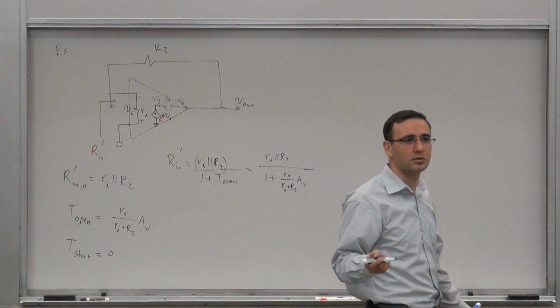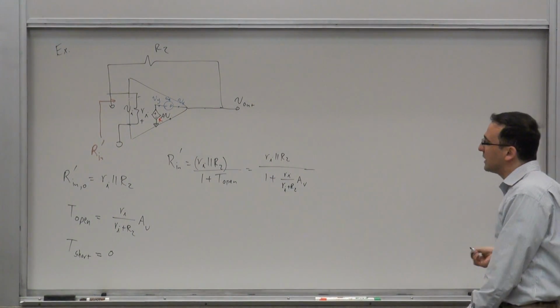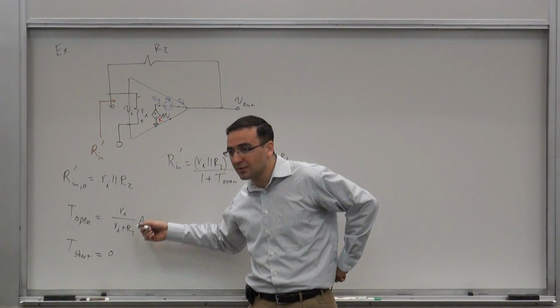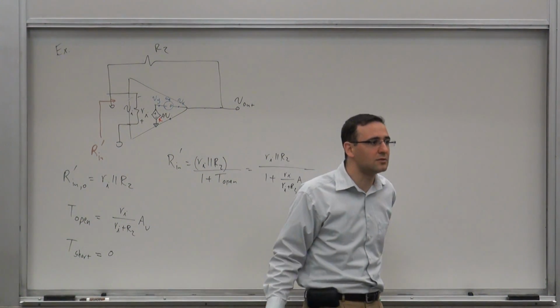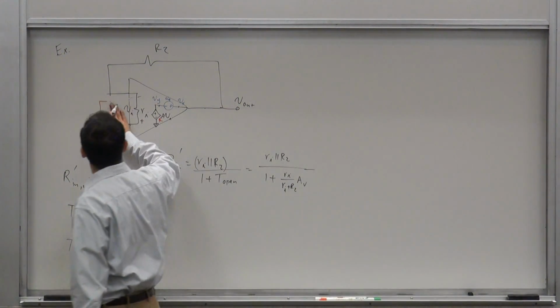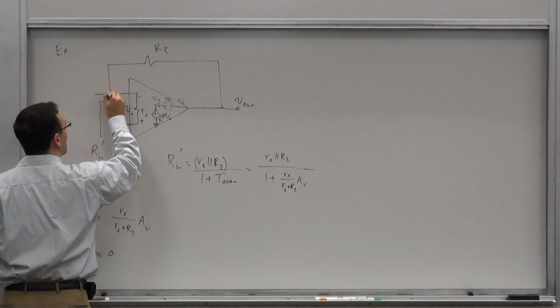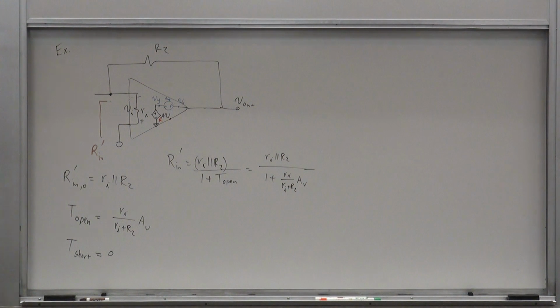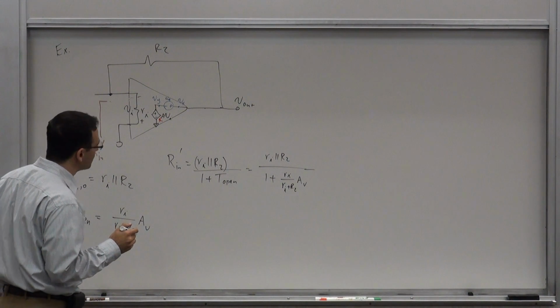You make a shunt input. Now, because of the way we've done it, this is a pure shunt, right? Because T short is 0. So this is a pure shunt. Pure shunt is another way of saying that you are exactly at the summing node, where the two currents are subtracted. Or pure series means that you're exactly at the difference calculation point of two voltages.